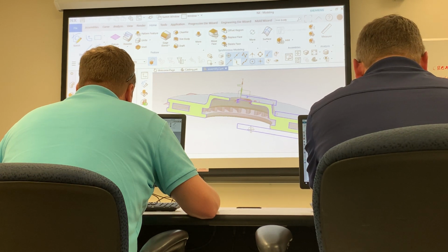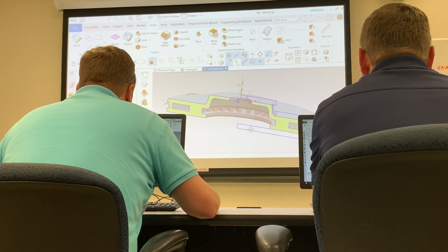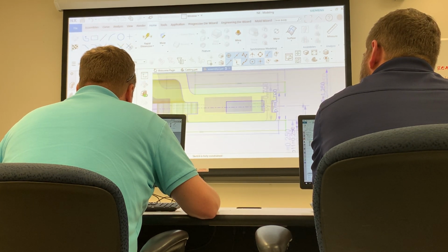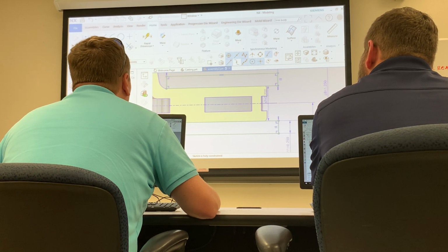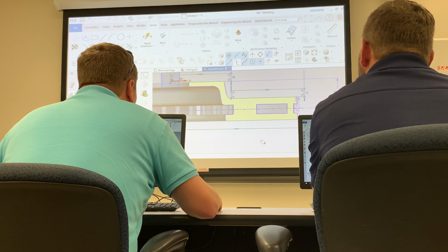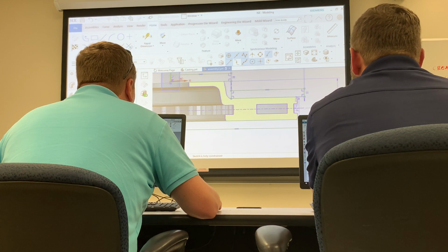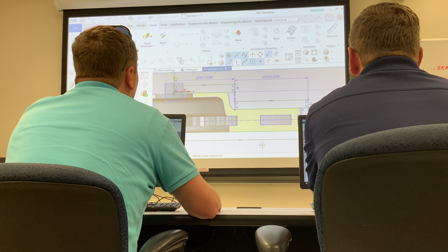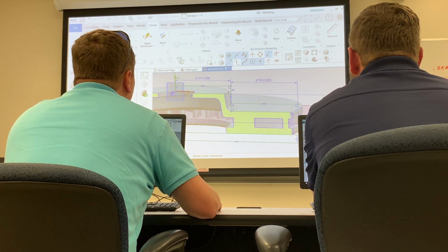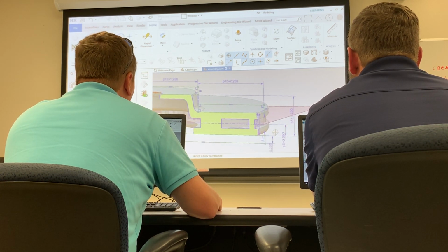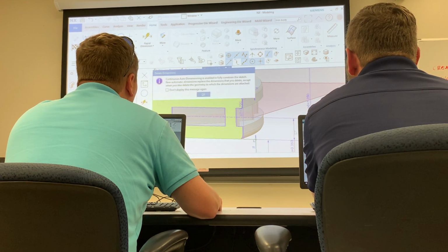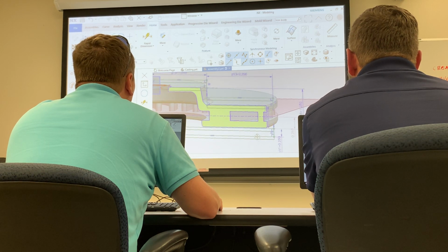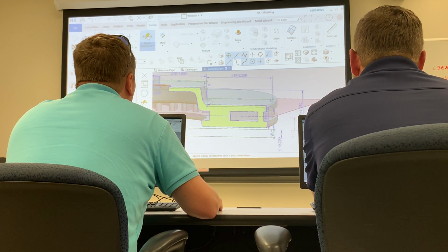Yeah. I was going to say, can you redo the bottom square that you did? Just the dimensioning of it. Yeah, so the dimension that's critical is this. The other dimensions are there to keep it from moving around, so that it'll hold it in space left and right. How did you get your center? I put this datum plane in here. And when I dimensioned the first, this 0.35 is actually the thing that keeps everything nicely centered. See, if I take that out, all this stuff can move around. Yeah. All right, so it's the key dimension.